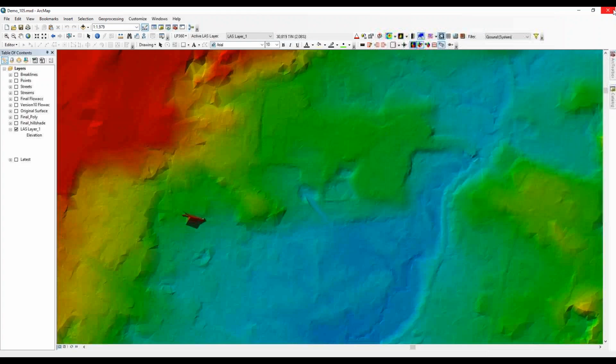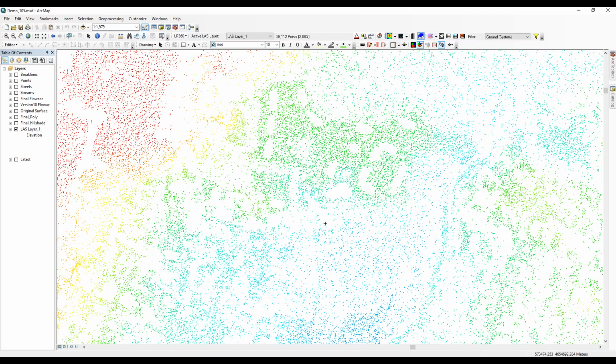So the first thing that we're going to want to do with this surface is to turn it into a raster. And that means taking all these points, this is actually the representation of all the points on the ground, and taking that surface and converting it into columns and rows of pixels essentially, or cells, that we can then do really cool math with, right?